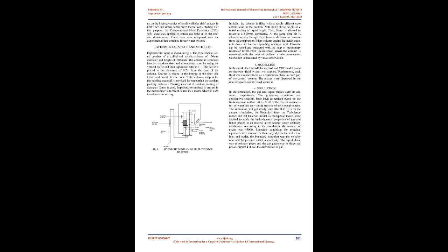characteristics of the split-cylinder reactor because of several beneficial features such as high and flexible capacity, simple conceptual design, low shear rate, high mixing performance, best contact between various phases, less reaction time, acceptable heat transfer rate, and low energy and maintenance cost. Conventional airlift reactors are not adequate to carry out variable volume processes, since it is not possible to achieve liquid circulation in this reactor until the liquid height is higher than that of the downcomer. In order to carry out the process of variable volume, they proposed the concept of the split-cylinder airlift reactor.